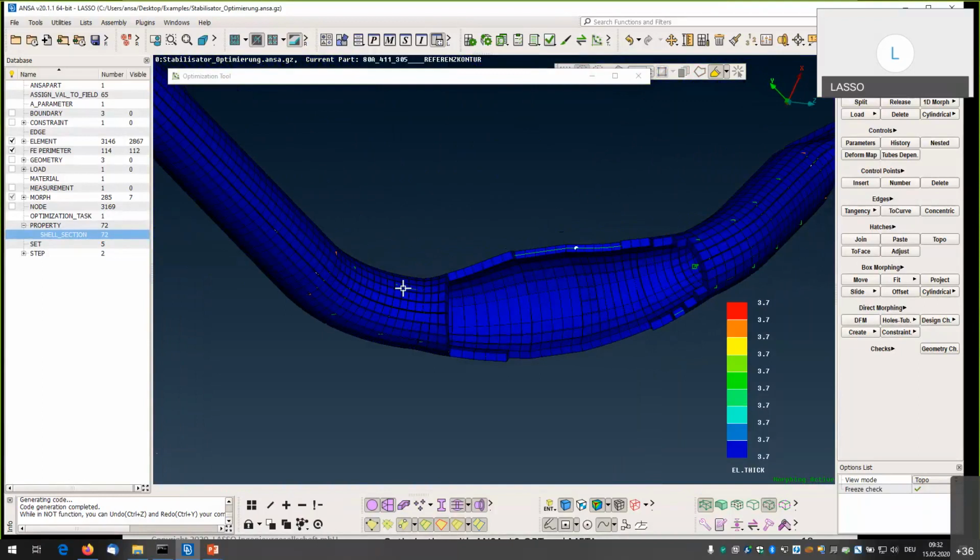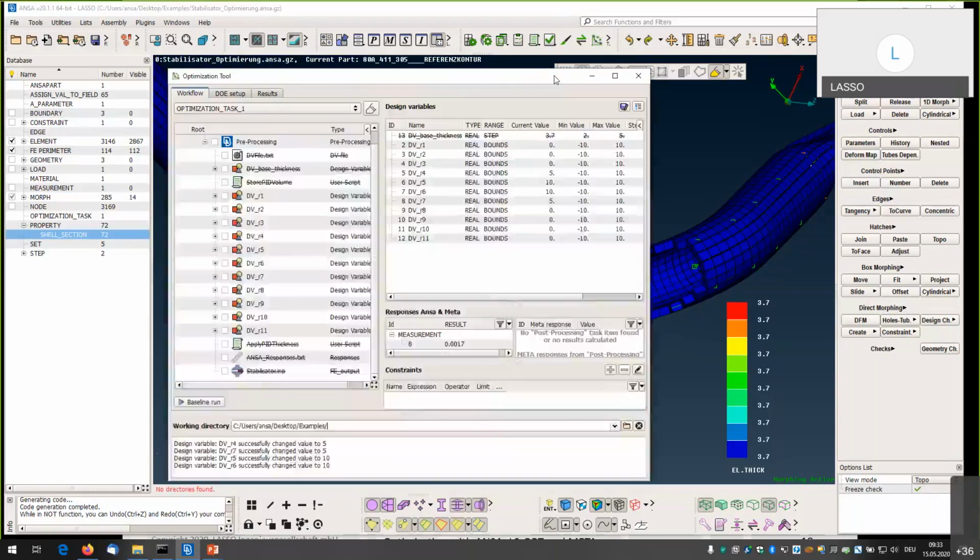So like when we do a hydroforming, when we increase the diameter, actually the thickness in the higher diameters decreases. So we thought, how could we do it in the optimization task? Just do an undo. And for this, we use a small script.